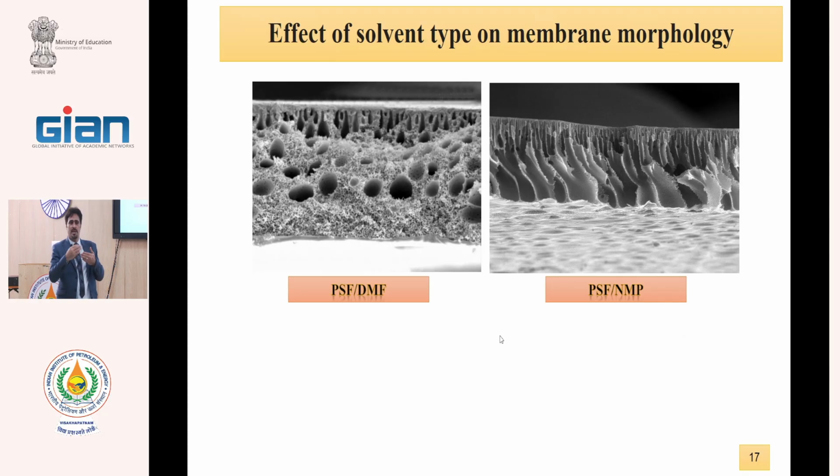In some cases, after preparation of the first layer and drying, we can use the membrane as a support, and the second layer will be cast on the solid first layer. There are many methods for production of dual layer and three layer membranes from polymers.